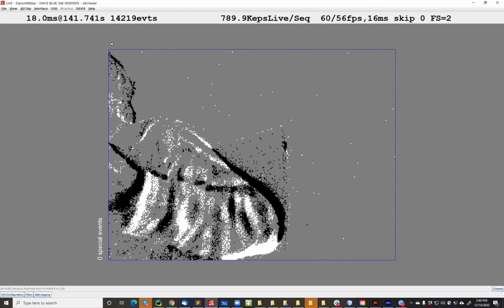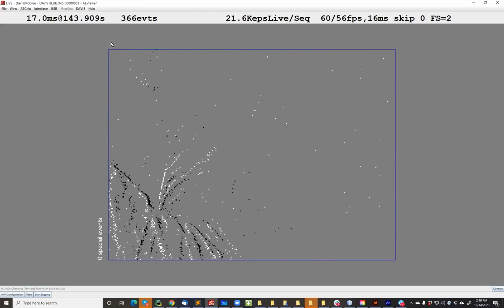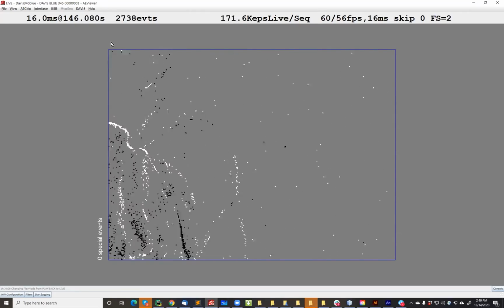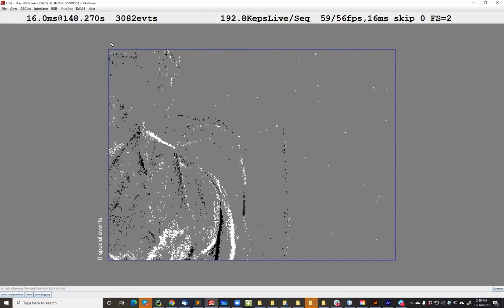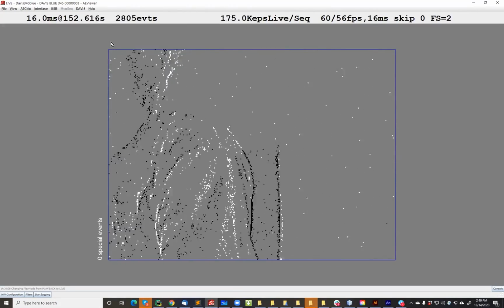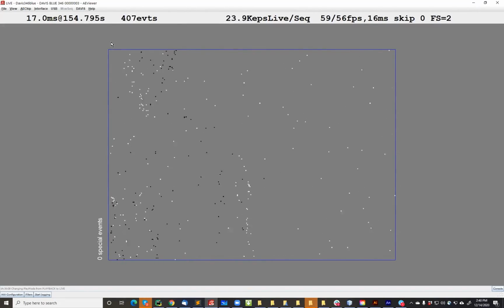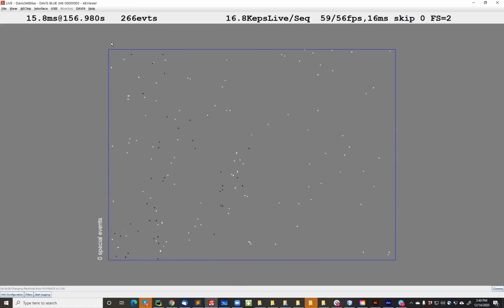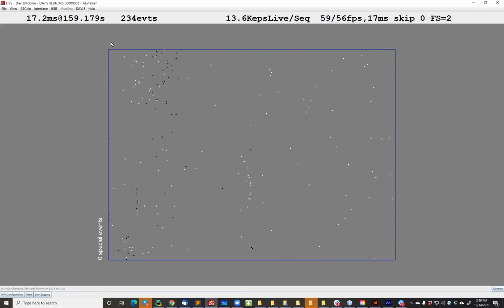Every smartphone has this accelerometer gyro chip in it that gives the smartphone the sense of how it's moving in space, how it's rotating and how it's accelerating. And you can buy those chips for about $1 now, and they burn about 1 milliwatt. They're really cool. So you can basically build your own electronic vestibular system, right?